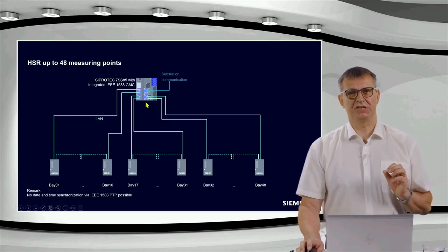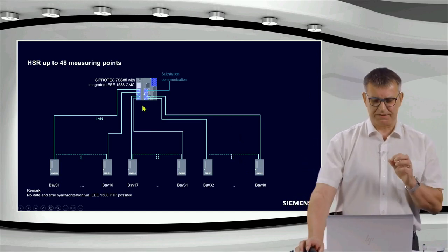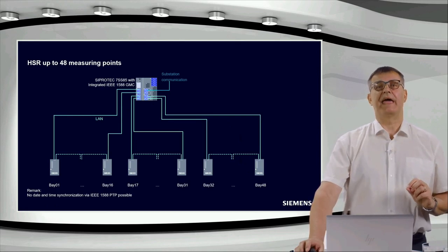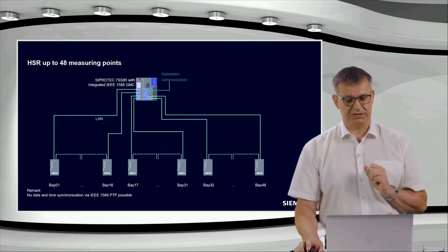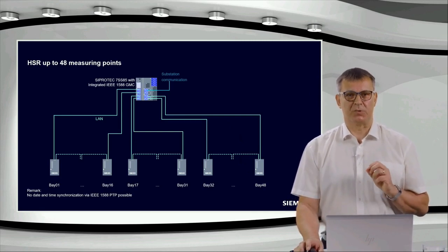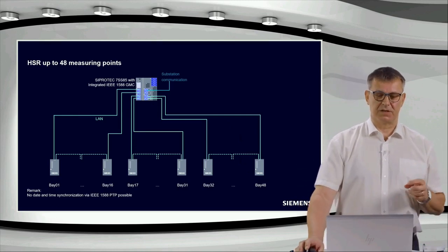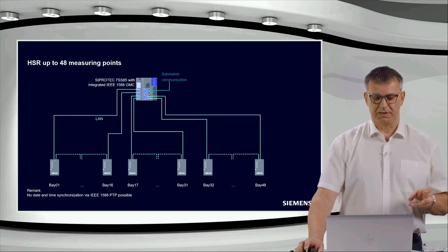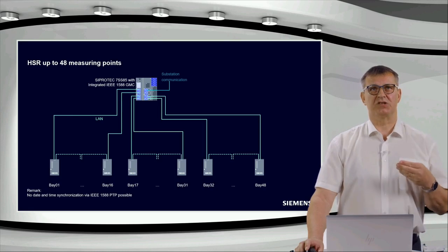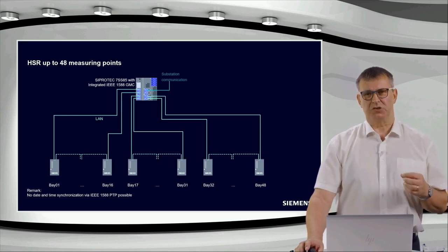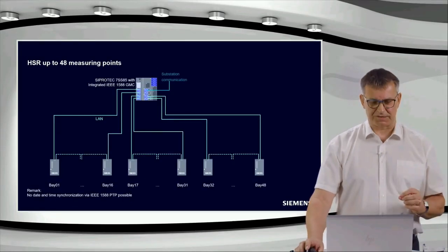Let's come to the synchronization of the standard measured values. You know, it's a differential protection. And the main algorithms, as you have learned in our second tutorial, are the spontaneous algorithms, the algorithms based on really momentary values. And to make such a distributed busbar protection, such a differential protection, the standard measured values, the momentary values, must be synchronized on a very high level.